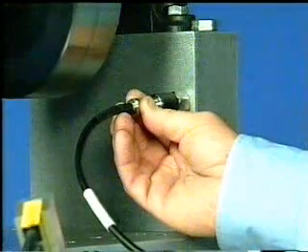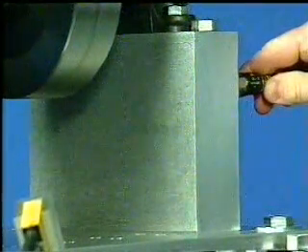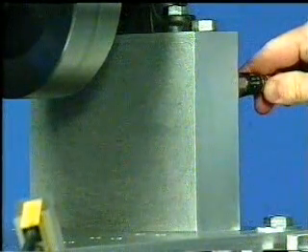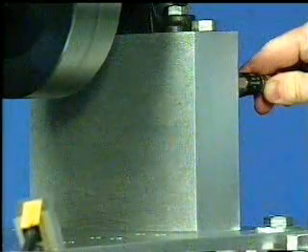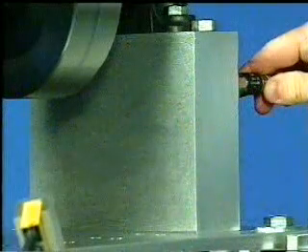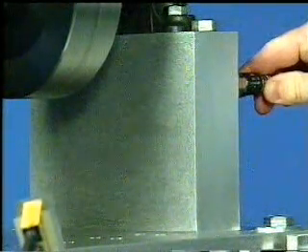Because of this, there is a difference of 180 degrees when the sensor is flipped from one side to the other. So it is very important to take into consideration the sensor orientation, especially on axial measurements. If the orientation is not the same, be sure to subtract 180 degrees from the measurement to correct for it.